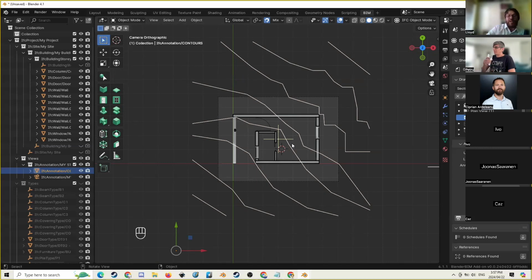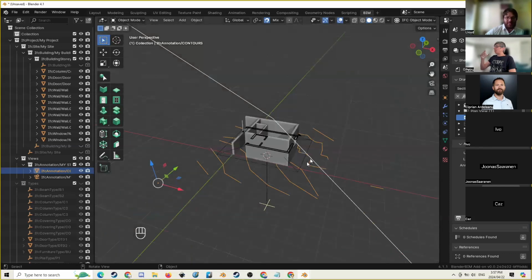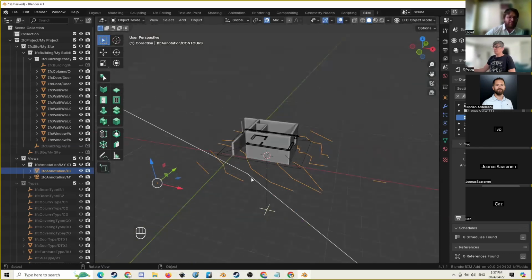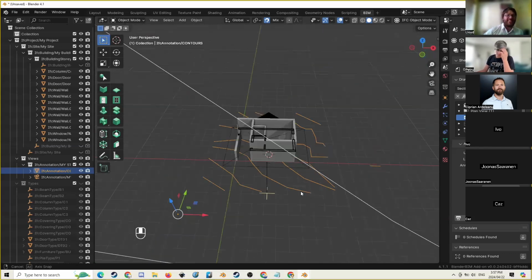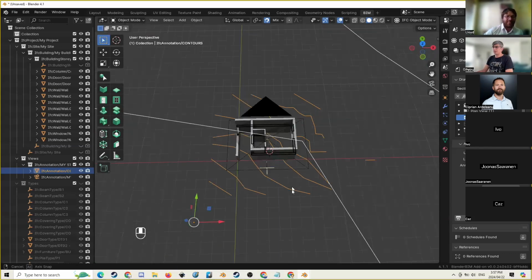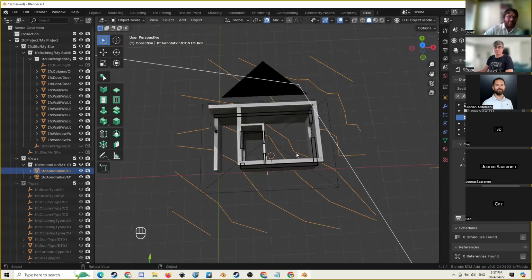So what I would do separately to this is actually model the, so I've kind of drawn this as half-meter increments, I would actually model the 3D terrain as well, and then store that with the IFC. But that's what I'm saying. It just doesn't represent itself properly when you cut the terrain at different levels. I don't know, it's something to do with triangulation or something. It's always different from the contours that are provided. And I found that in Revit, in ArchiCAD, in every program I've ever used.